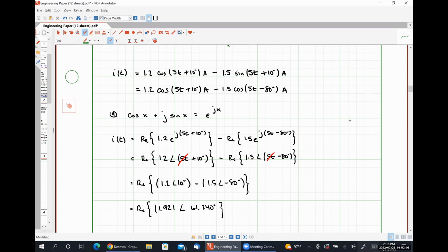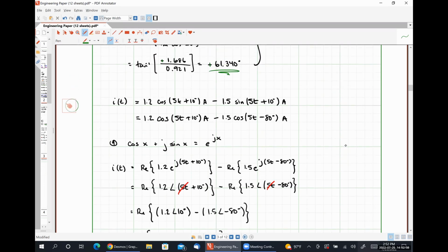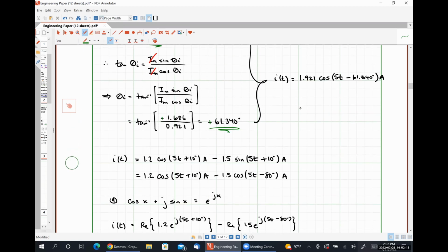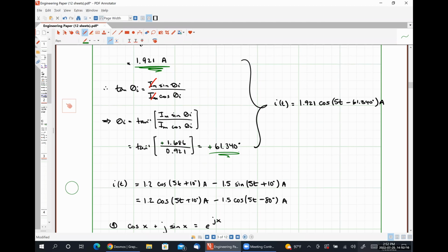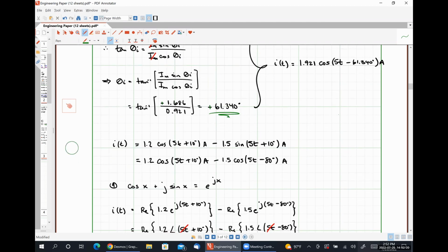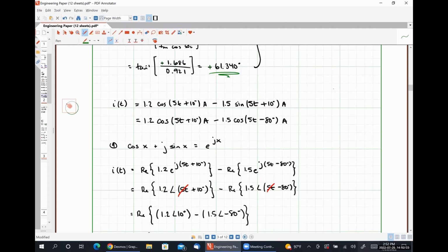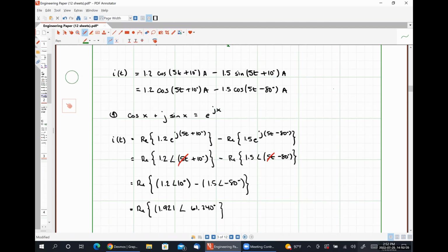Okay, so we get the same magnitude and the same phase angle as all of that trig and stuff, just using complex numbers to represent our sinusoidal function. Okay, this is the key of circuit analysis in the frequency domain.